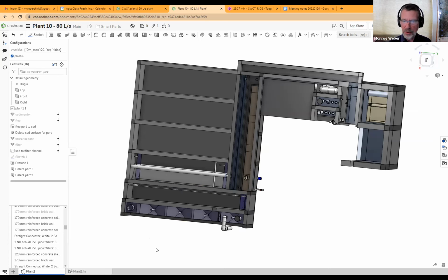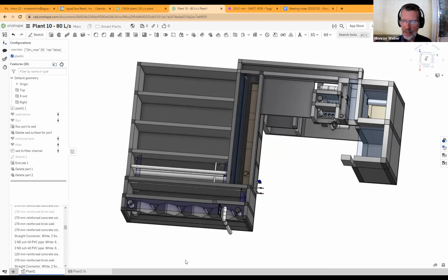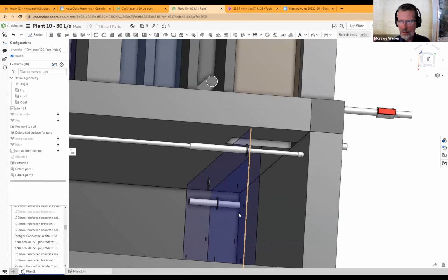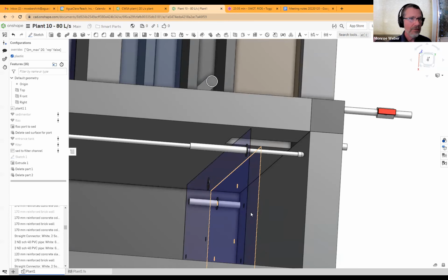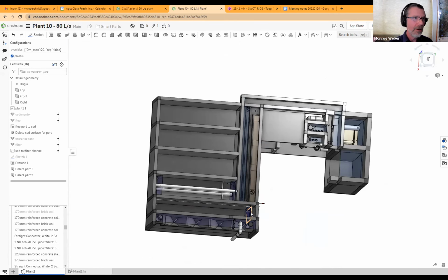So for example, if you look into this tank right now, you'll see that for the flocculator, there's only 2 pieces of plastic here making the little baffles, and all the rest of them aren't drawn. That's because I have rep set to false, and I do that so that I can move around here and show you things quickly, because it starts to get slow as we start making all these pieces show up.